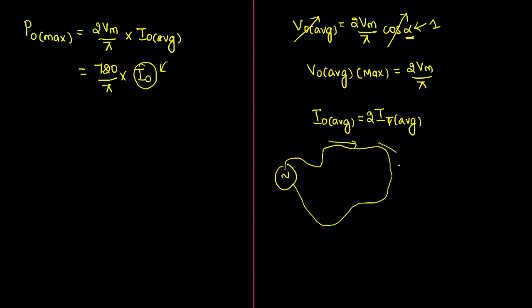What can be the maximum power that can be delivered? So in that case, I cannot maximize the current, because if I double this current, if I take the output current equal to 2 times the thyristor average current, then what will happen? The current that can be handled by the thyristor is only 100 ampere. If I multiply it by 2, then it will become 200 ampere. This much current cannot flow through the converter. So I cannot say this is the current handled by the converter. So this is the wrong answer.